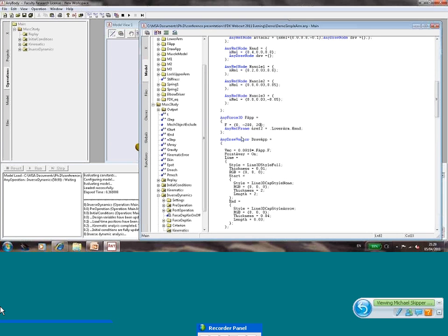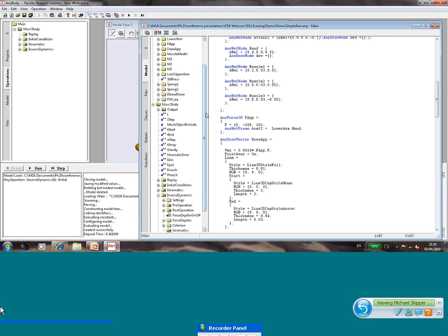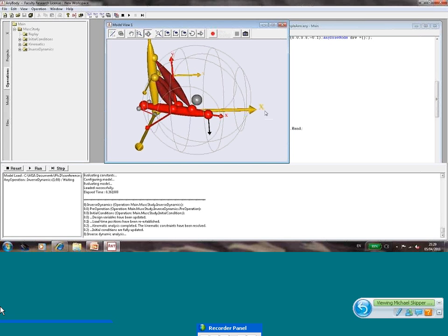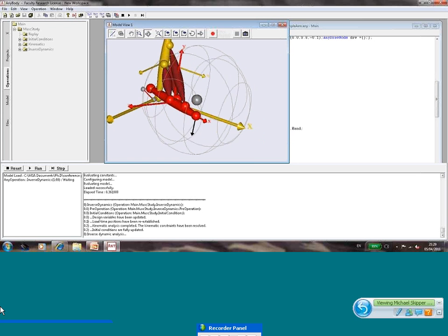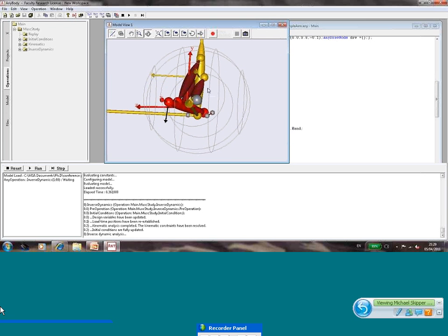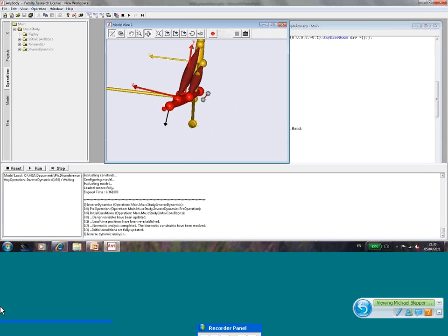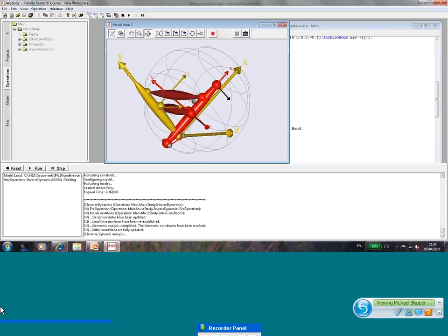Reset and reload. Then I will step it to the result, and I will rotate the view here a little bit, so we see it from the end up here. Now we actually have an uneven, or rotated, lower arm relative to what we had before, and this was completely controlled by the external load. Just to illustrate that even with just these two simple springs, this is behaving much differently than just a revolute joint, when the stiffness is low. Okay.